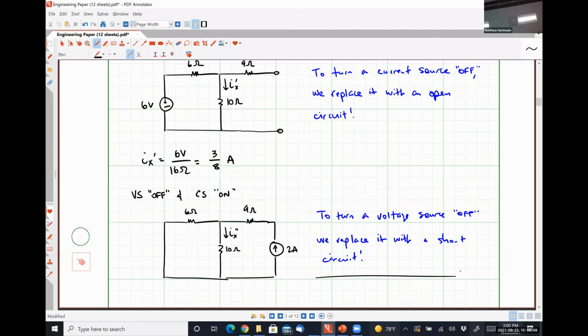There will be voltages in the circuit because we have some amount of current passing through resistors and all that kind of stuff, and that's good enough to make things flow in general. But explicitly for the short circuit itself, Ohm's law has been satisfied since any amount of current multiplied by 0 resistance gives us that 0 volt drop. If that weren't true, current couldn't flow through wires, right? Well, we're treating wires in this class as if they have 0 resistance. Really, it's very, very small in comparison to the other stuff.